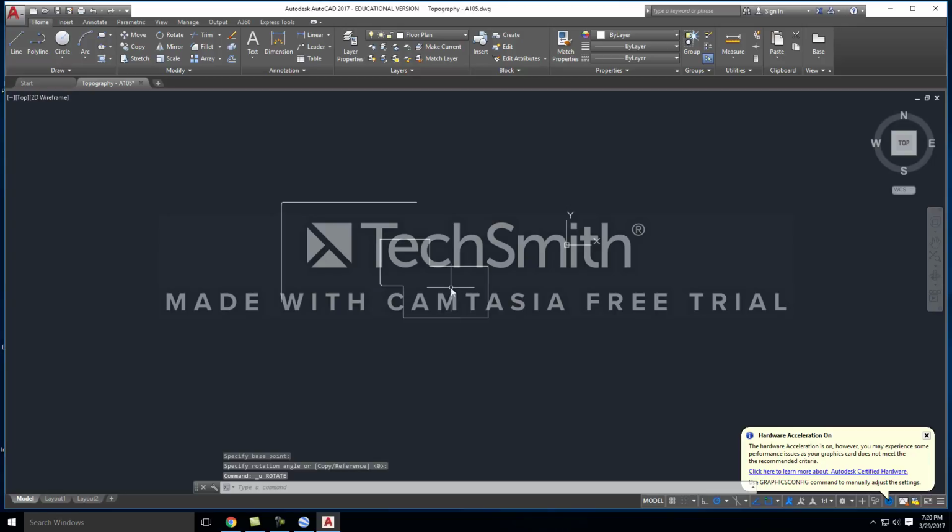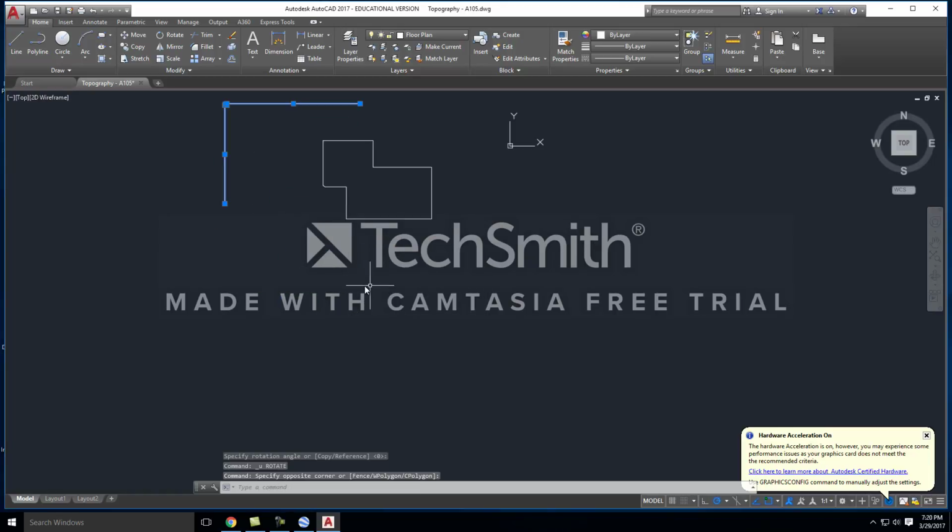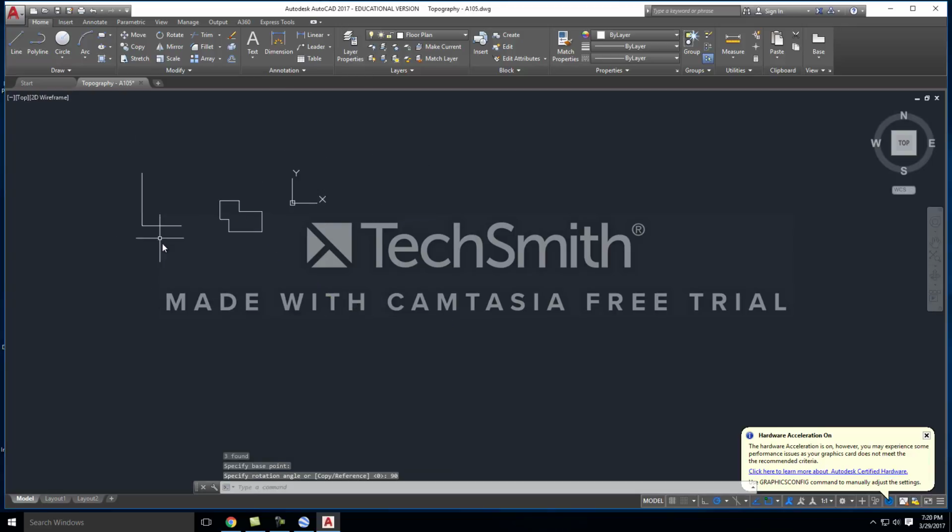You could either just click once, and that will place your object wherever you clicked. You can also specify the amount that you want it to rotate. So I hit RO for rotate, and if I want it to rotate clockwise, I would just type in something like 90 or 180 for the amount of degrees that you want it to turn. You can also type in -90 or -180, and you will get it to go the opposite way. Typically you work in 90-degree intervals, 45-degree intervals, but of course you will run into times when you don't. Again, I can just specify my rotation angle. I type in 90, enter. Notice that it turned exactly 90 degrees.